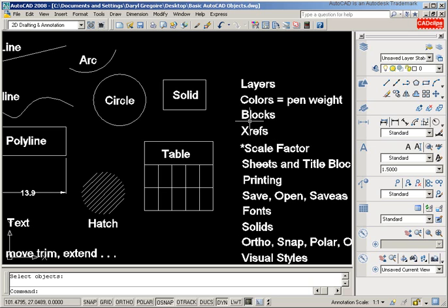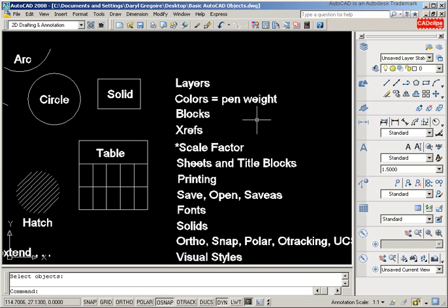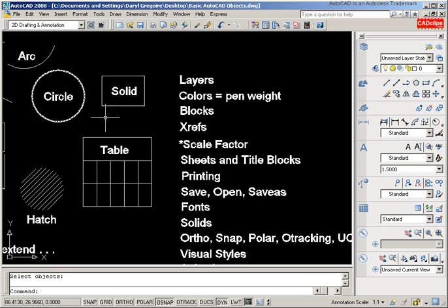You can save that block outside of your drawing file as its own DWG file, and then you have a block library where you have all of your components. And the whole idea, of course, in AutoCAD is to have this very vast library of blocks where you can just start inserting objects. You don't have to redraw them from lines and arcs all the time because you've already got it created as a block.